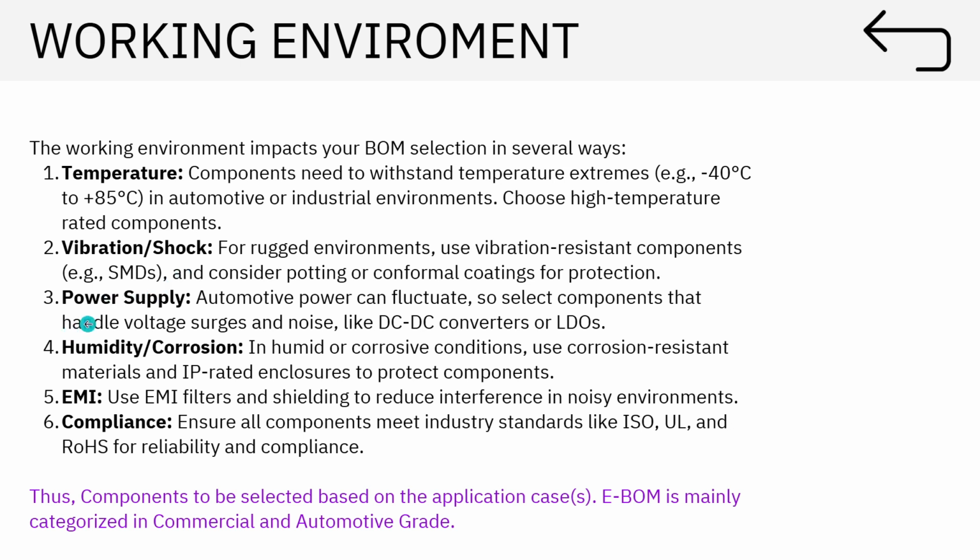Then it comes to humidity and corrosion, right? So maybe it is for an outdoor application. You are making, let's say, an air quality monitoring system, where you have put a sensor, then you have an IoT device plugged in with an interface. Since it's outdoor, you sometimes have to use a conformal coating also because of the humidity. So those sort of things you have to keep in mind.